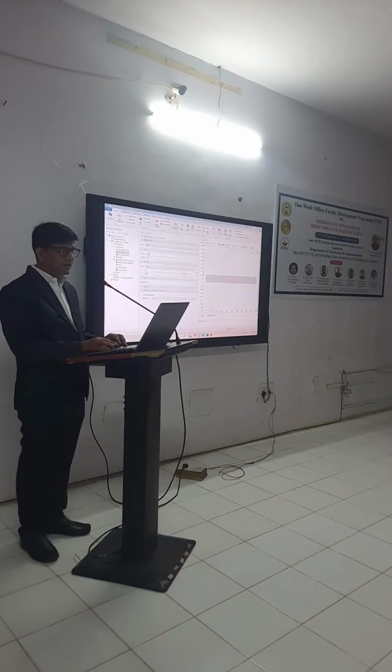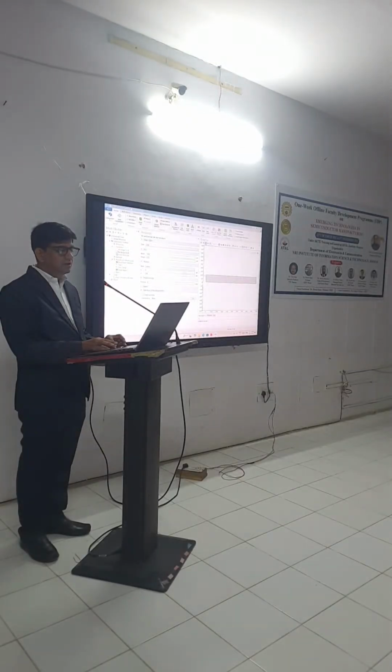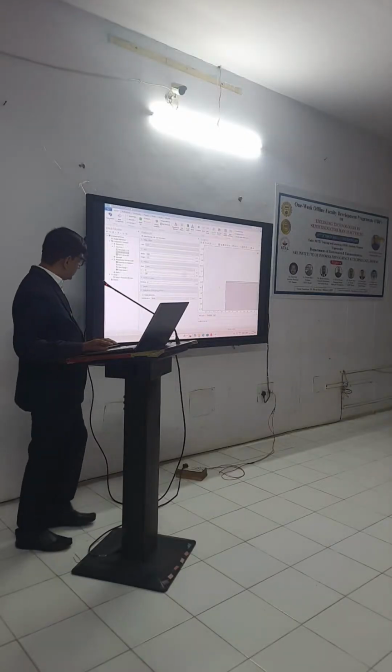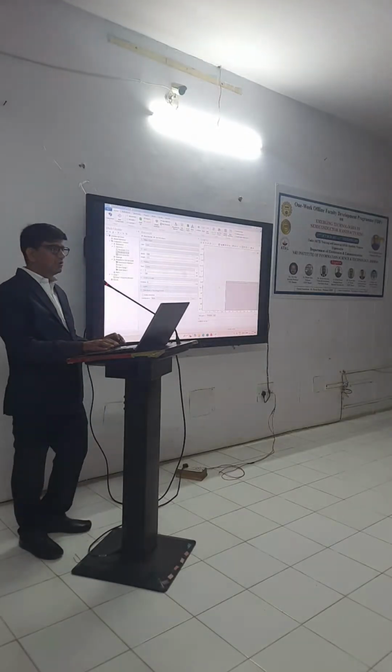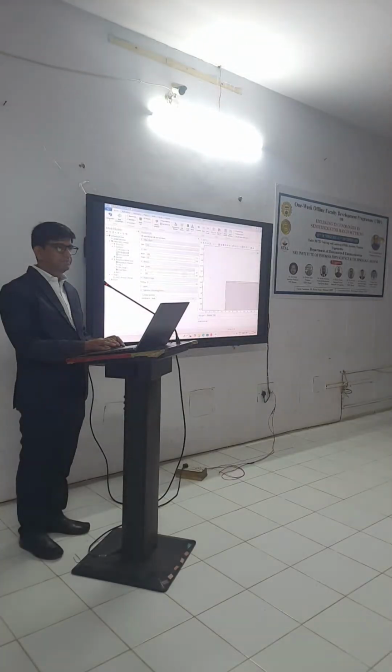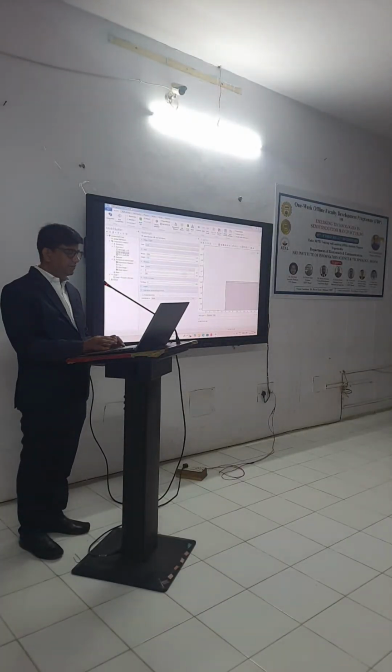Build selected. So what I have, if you zoom out, you have this PET substrate, and over the PET substrate you have a bottom electrode. Then next we have to have a piezoelectric layer, that is the ZnO layer. So for the ZnO layer, again what do you require? You require a width of 1000 and height. What height is required? We require 2 micron thickness for my ZnO layer. So instead of 0.15, I will select 2.